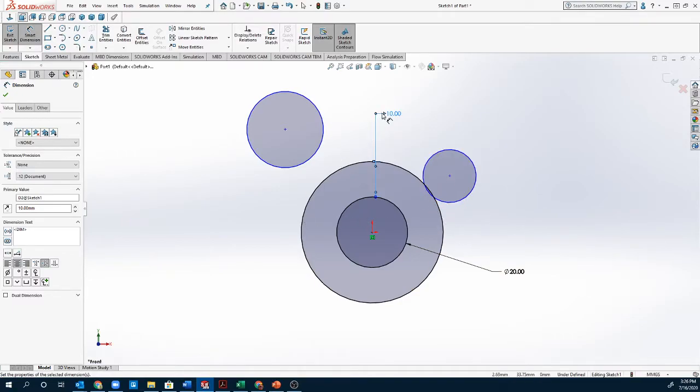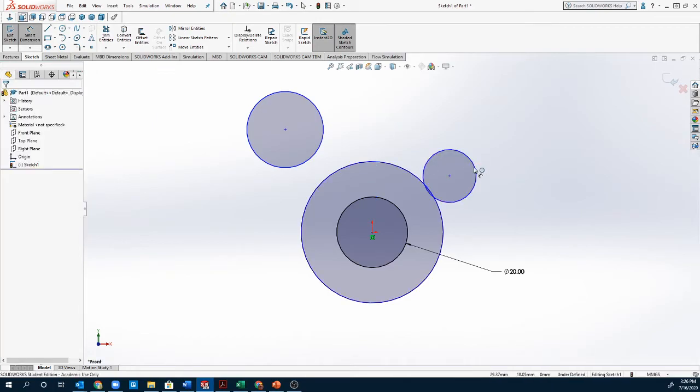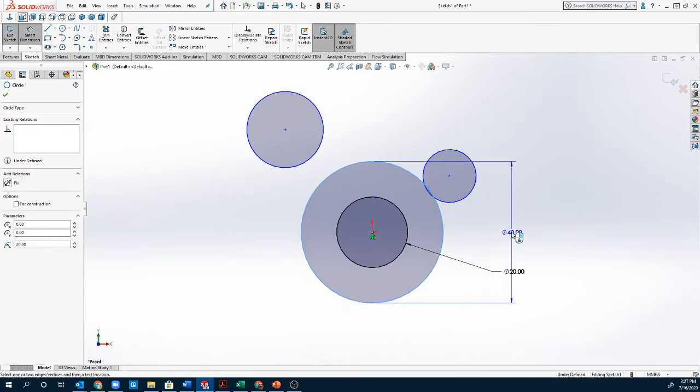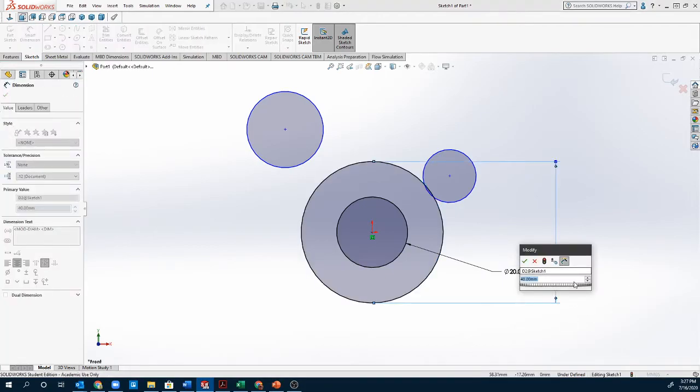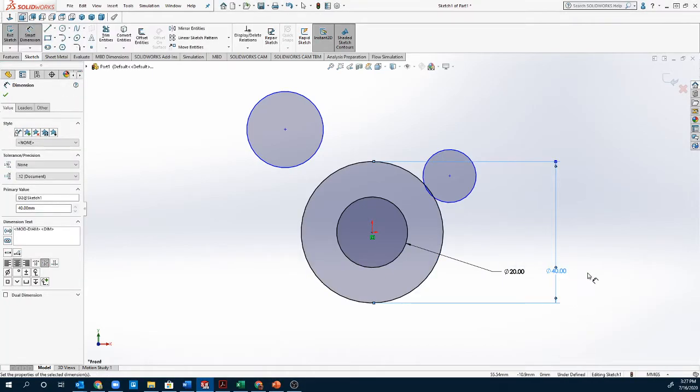Or an equivalent would be to click on the circle on the outside and set it to 40 millimeters, sorry, 40 millimeters. So if we set that, we get the exact same result as if we did it as the internals. Sometimes one is better than the other, depending on how you're designing things. If you're designing, say, a tire, you probably want to know the wall thickness of the tire, where the outer radius may matter, but you need to know how large the cut of the hole in the center is. You can use the offset method to do it that way.